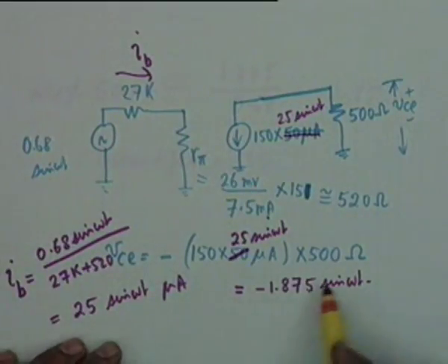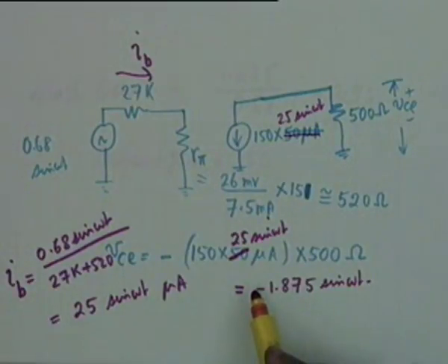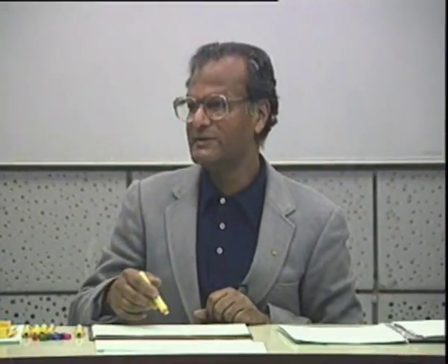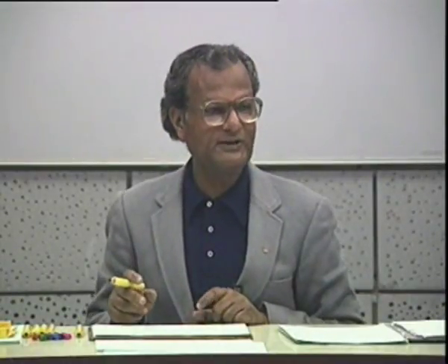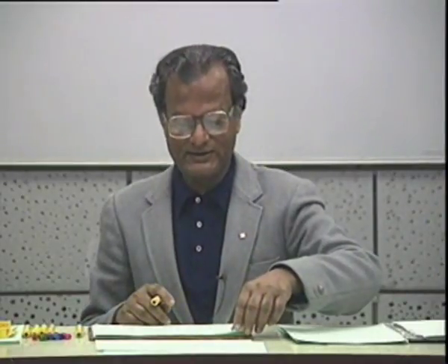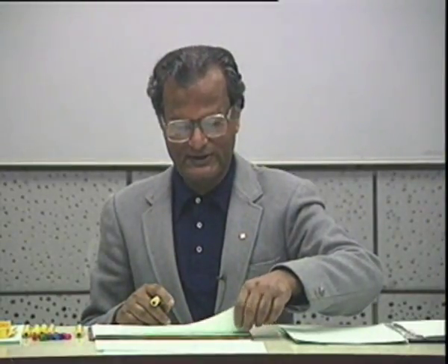But you must remember there is a negative sign here, which means a phase change of 180 degrees. In general, it may be 180 degrees or 180 degrees plus some other component phi. As you shall see later, when you take the transistor capacitances into consideration, then there is indeed a phase change which is different from 180. Therefore, there is a phase change here of 180 degrees.